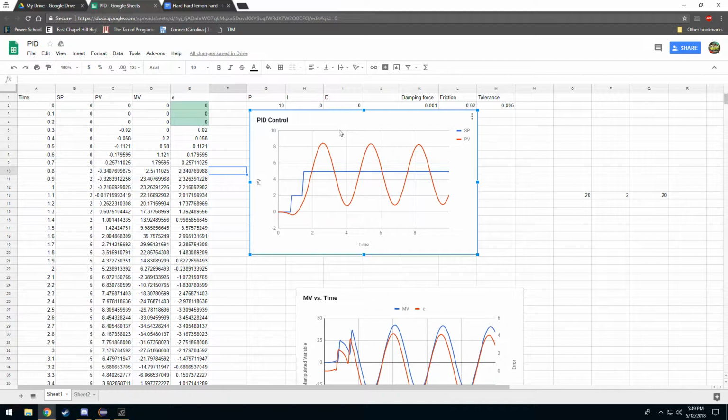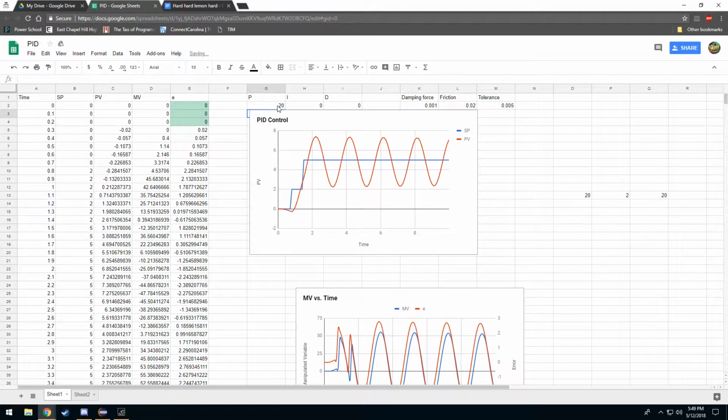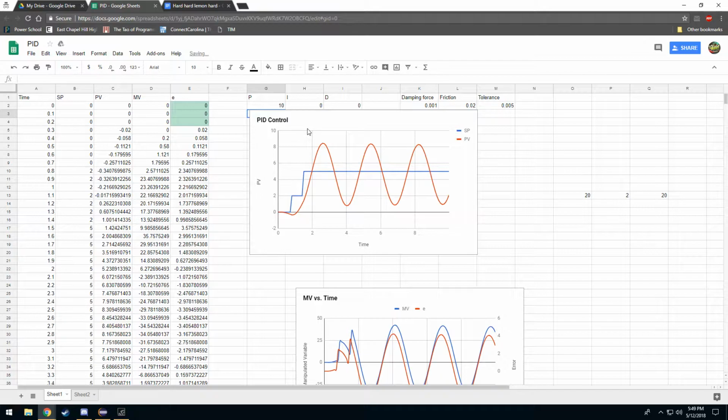That's proportional control. That's not good enough, because as you can see, it's good enough in some scenarios if you're able to tune it properly. If you mess with this, you can eventually get to a point where you might like it, but it's not going to be ideal because there's too much oscillation.